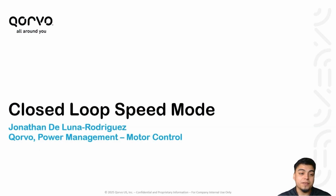This is part 5 of the sensorless FOC bring up chapter. In the previous video, we brought up the estimator in closed loop torque mode, and we confirmed that the handoff from open loop into estimator base control is stable. Now we're going to move into closed loop speed mode.